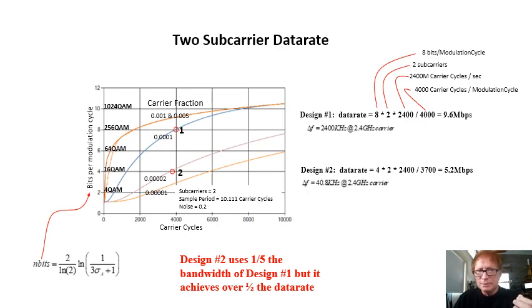The message here, as with a single carrier system, is that communication system optimization can be readily performed using the covariance matrix for the demodulated A and B parameters. That is, we can look at a family of multi-carrier designs, all with a fixed BER, and ask which system has the highest data rate for a specified system bandwidth.